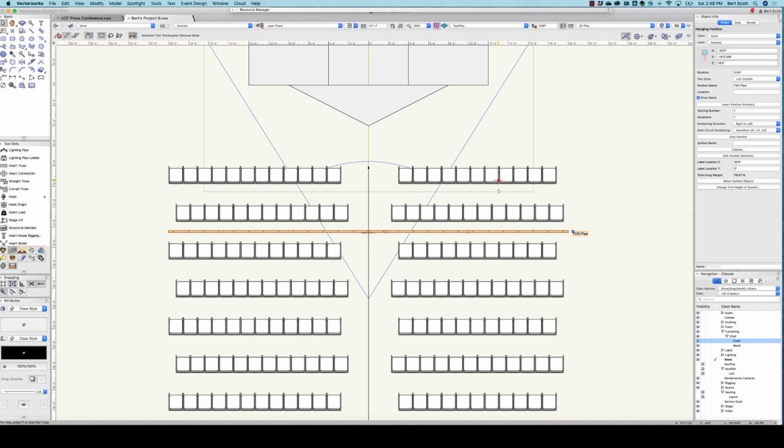Once you change the pipe to a hanging position, you no longer have most of the physical attributes of the pipe itself. You notice I can no longer change it from a single line to double line. I can no longer change the tick marks. So the physical attributes have to be set before you change it to a hanging position. But now I do have hanging position options like automatically numbering the lights or things like that. So the hanging position has different parameters than the pipe.